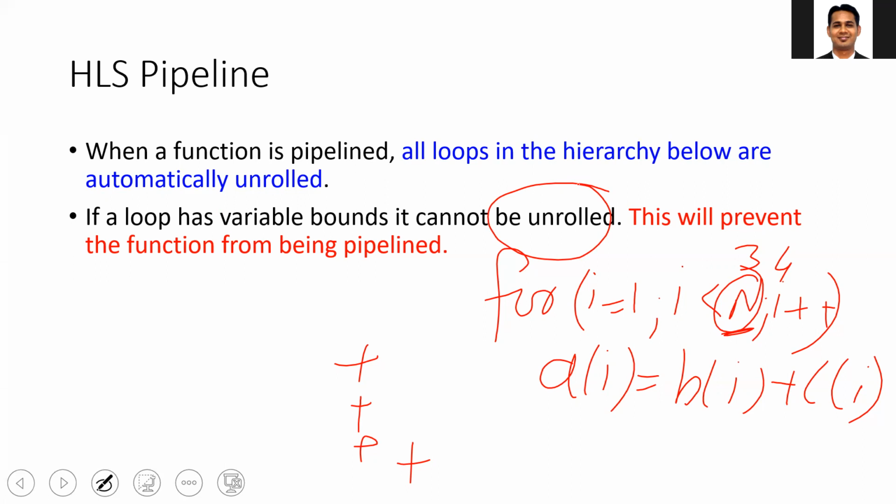You might be applying the HLS pragmas, and if you look at the warning, it says that this function cannot be pipelined, and you will not get the desired result. So you need to make sure that you take care of this issue.